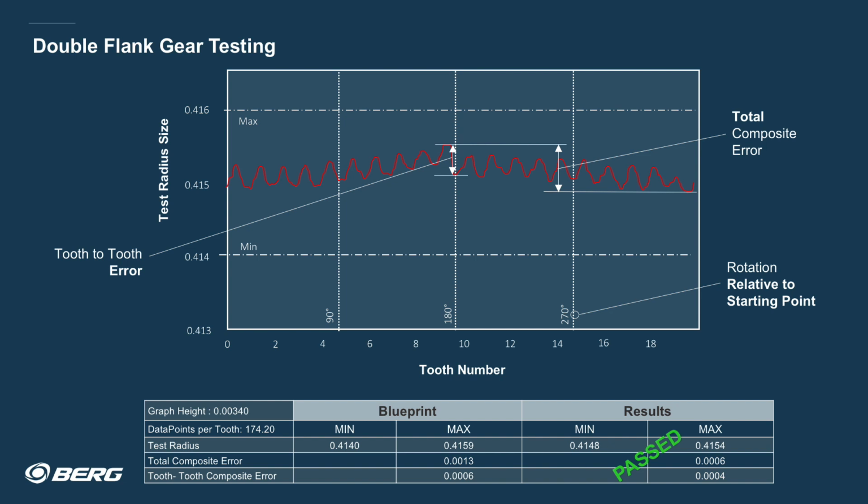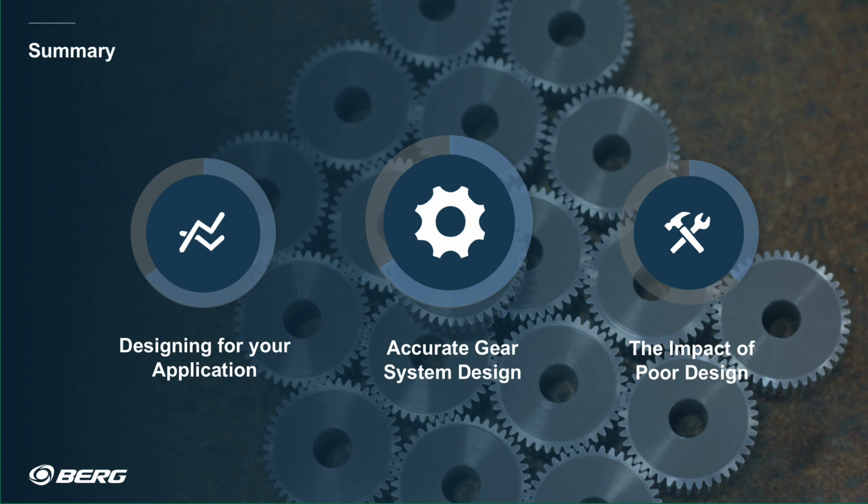The theory is that a perfectly formed tooth will show no center distance deviation. Therefore, this test accounts for profile, pitch, lead, tooth thickness, and total runout.